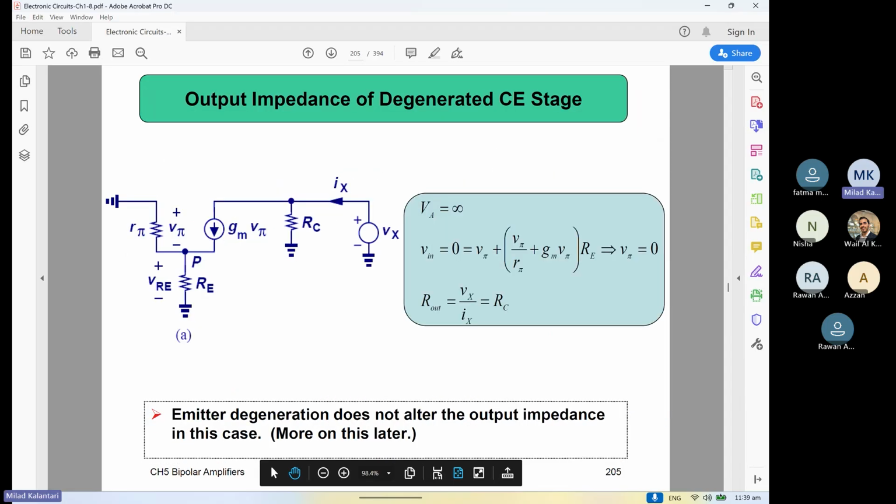Why do we care about this? So it comes back to the initial problem: you need to design an amplifier. You remember you had the microphone, and you model the microphone with some voltage source, but it has some limited output impedance, right? There is a voltage divider between the impedance of the source and the amplifier, right?